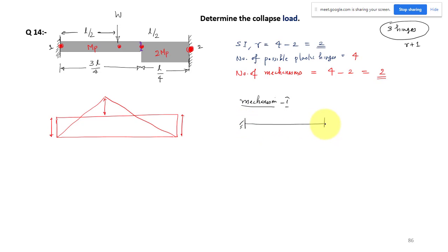possible plastic hinge. So we can have two hinges. The first two hinges will be forming at the support, and you increase the loading. Further you apply the load, then the third hinge may form at the midspan, wherever your point of action of the load is. At that section you have a peak moment, so that section may reach your plastic moment. This is the first possibility.